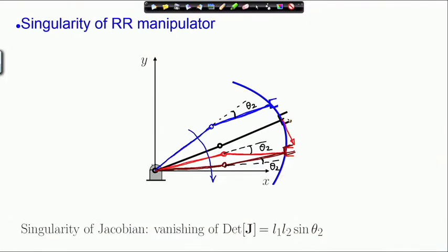You have to put additional constraints on the velocity of the actuators or the actuator rates, so that your motors or actuators do not get saturated. In that case, you lose on the path, or you can lose on the velocity that you desired on the path. So, there is a trade off. If the path is too close to a singular configuration, then you will lose accuracy on that path.